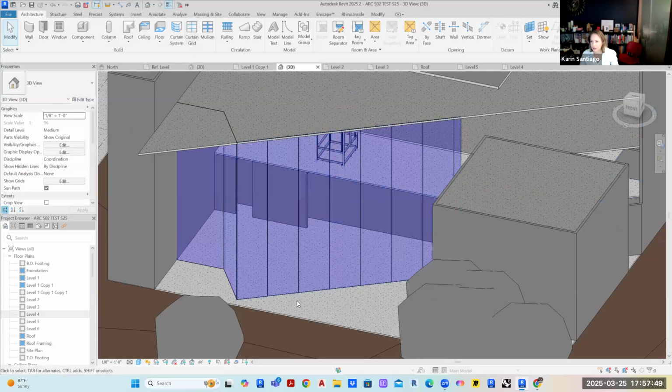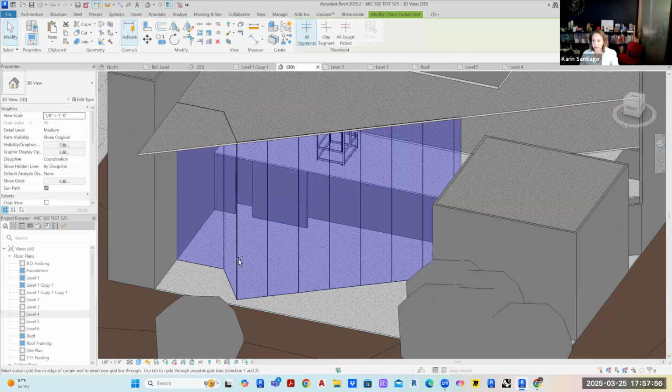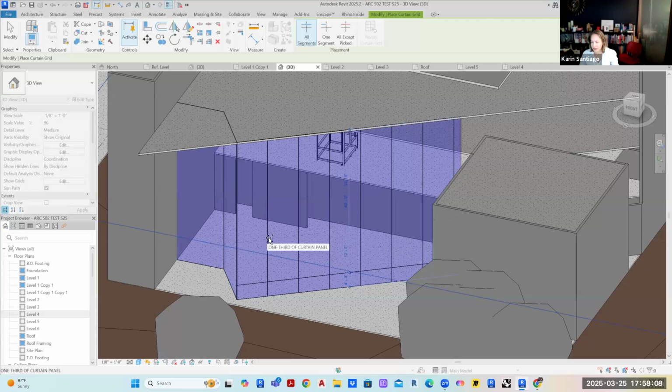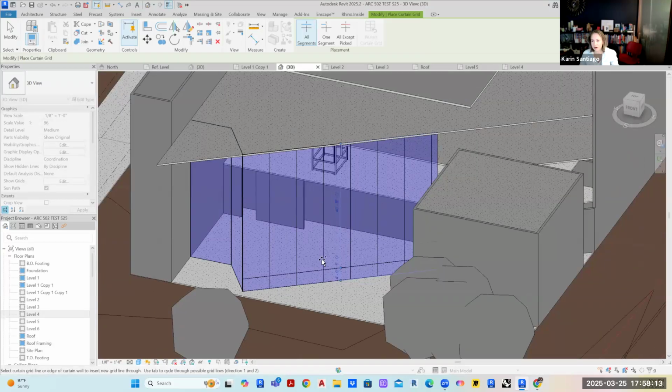I don't have to just divide the curtain wall in the vertical. I can do it in horizontal segments as well. So you can just grab the same tool and position yourself to get some of these. Generically, normally you'll want to match potentially the datum lines in your project. Those are the levels on your building. So I'm just going to put a few here just for the purposes of the conversation.